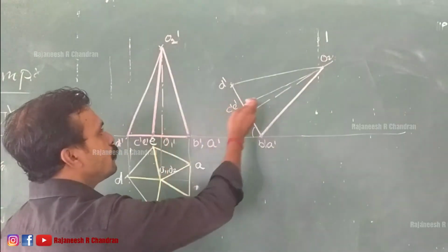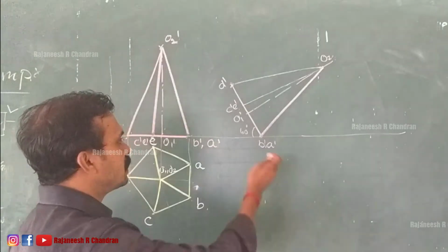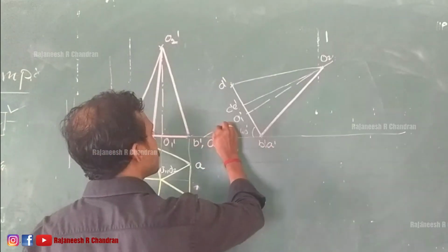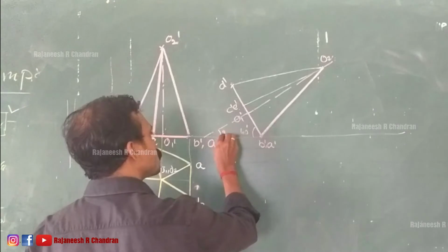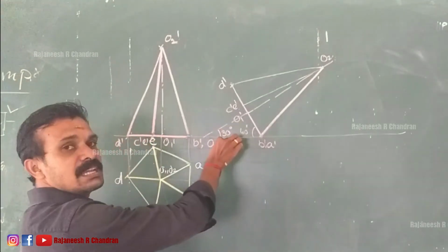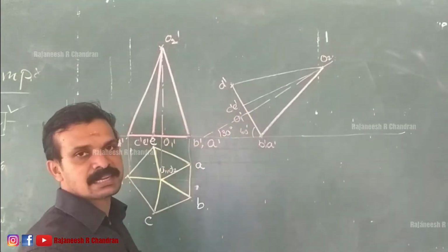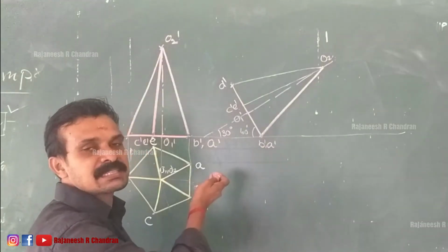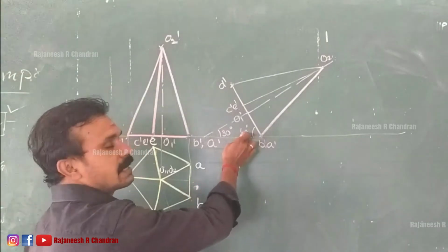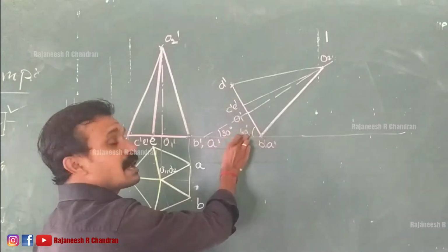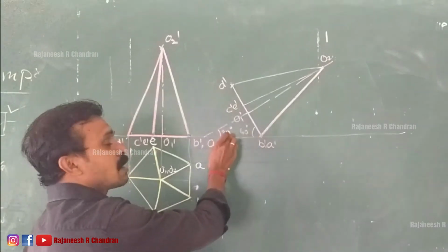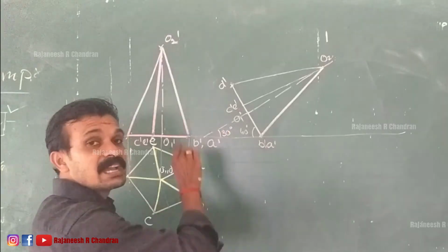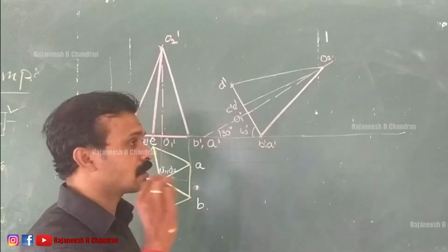So the front view has been reproduced here, with the axis inclined at an angle of 30 degree. So mark this also. Actually, this is the given value. Now the axis is inclined at 30 degree, but the method for drawing when the axis is inclined at 30 means the base will be inclined at an angle of 60 degree. So you can mark here as 60 degree and here as 30 degree, because this is the given dimension. That should have been marked.